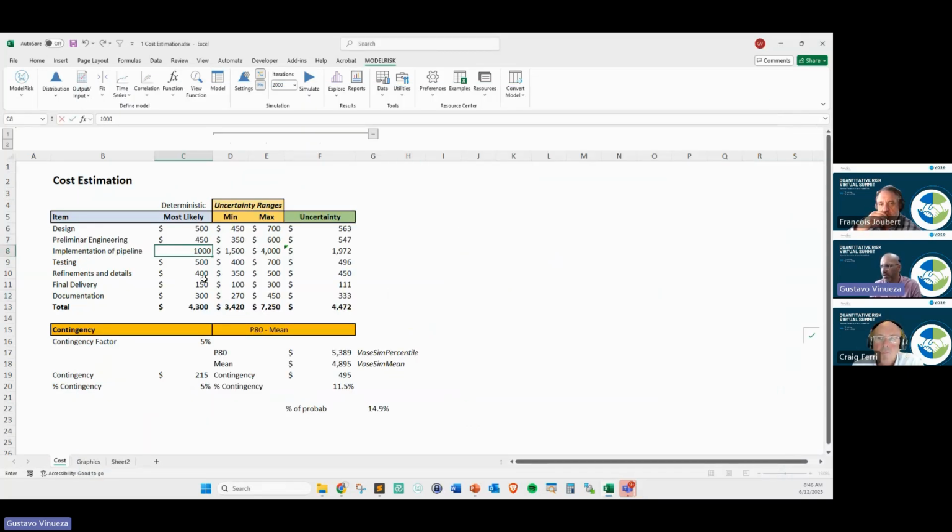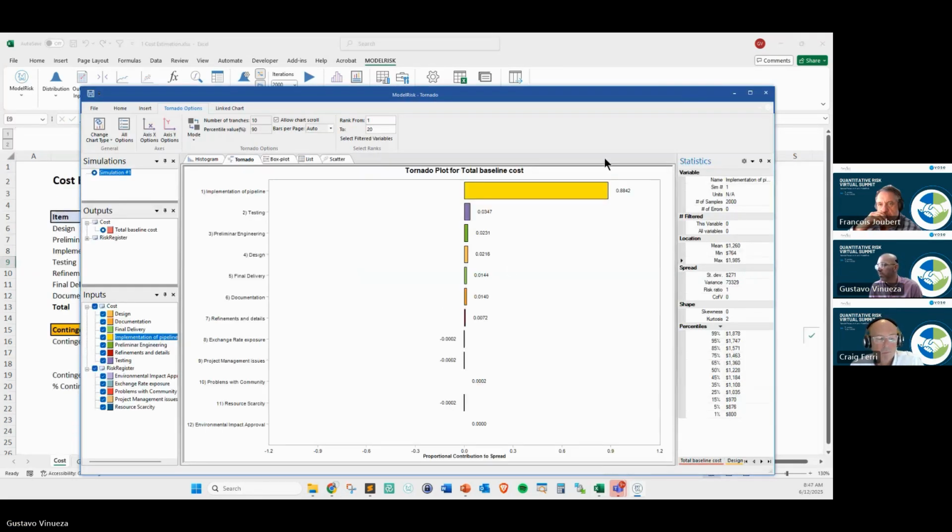What happens if I decrease the numbers here? Let's say I shave it in half, 750 and 2 million, right? I run the simulation, and that will be a good sensitivity analysis, right? And you see that now, instead of 95%, you have 88%. You see? And now the others start to get relevance. Why? Right? But you have a different tornado chart.